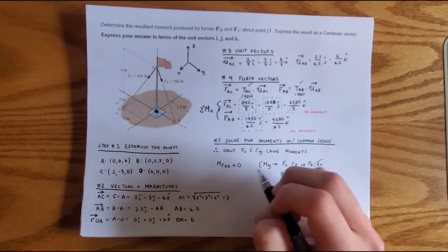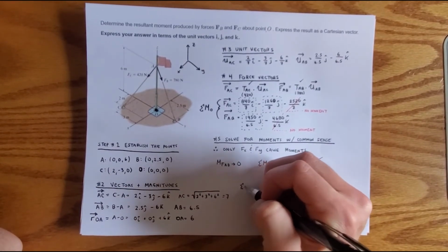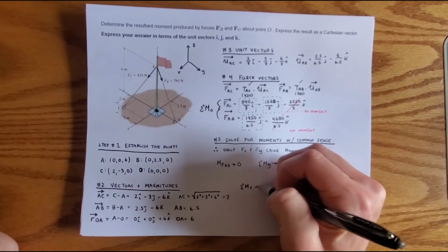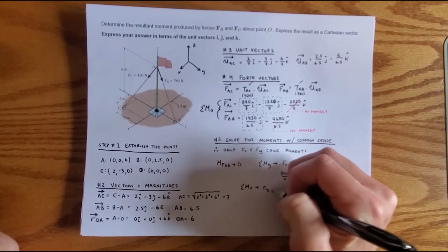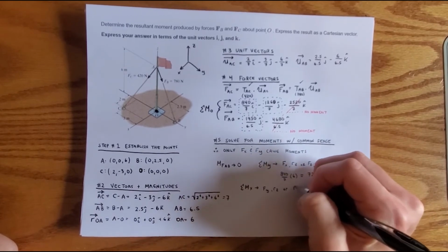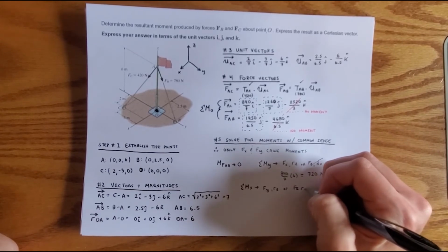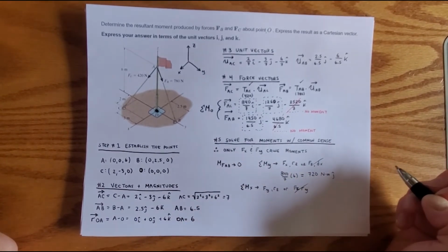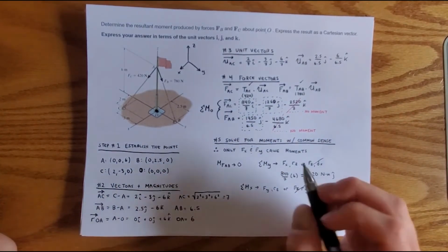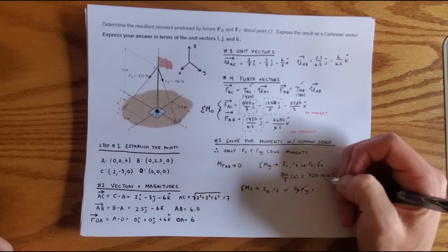If we then look at the sum of the moments about the x-axis, the sum of the moments about the x-axis are going to be caused by forces in the y multiplied by moment arms in the z, or forces in the z multiplied by a moment arm in the y. Again, this doesn't exist in this particular problem, but we do have two y forces and a z moment arm right here. So the sum of the moments about the x-axis is going to be equal to negative 1260 over